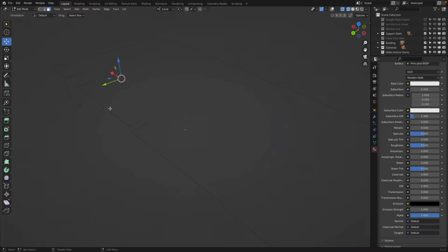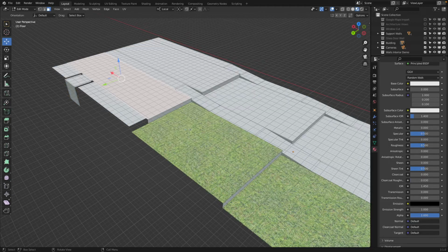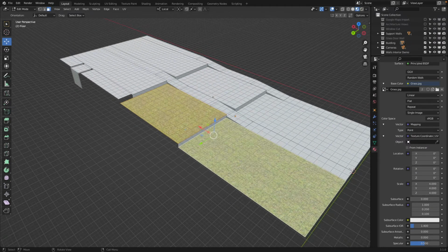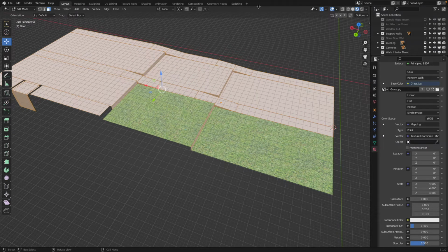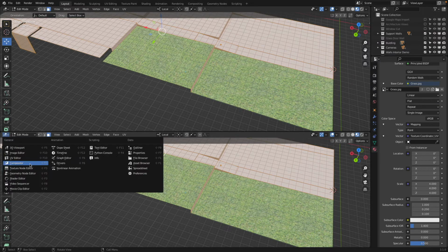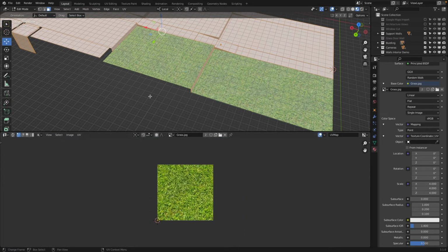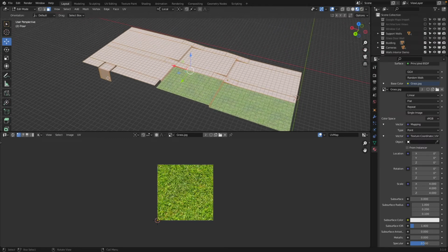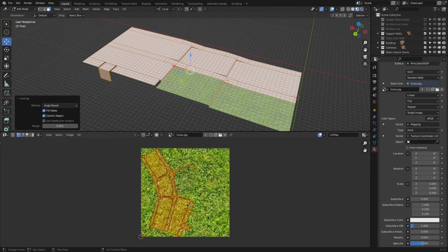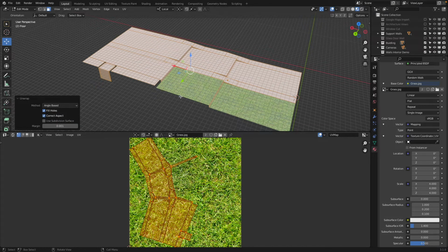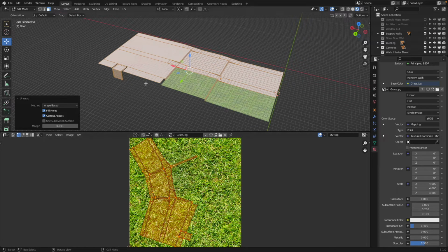So how can we now get the texture, let's say, over the ground, maybe for the concrete? So we go back to edit mode. I had this one turned off. There we are. Click, click. And now I say Control I, select the opposite. There we are. Very nice. So here I will say UV unwrap. Before I do this, right click, split horizontal down, UV editor, don't freak out. I'm only showing you what's going to happen. You see how this here also goes down. So UV unwrap. There, you see now, there's the piece unwrapped. Looks kind of twisted, but that's cool.